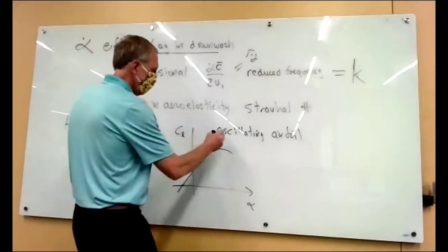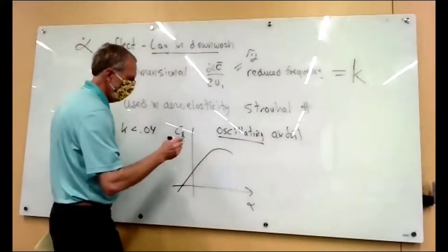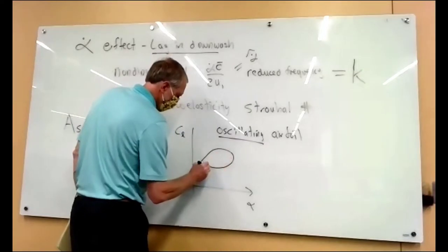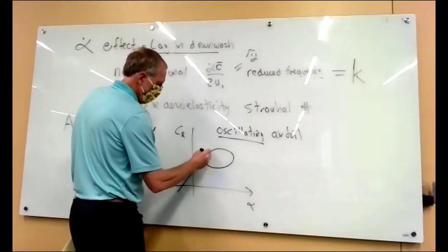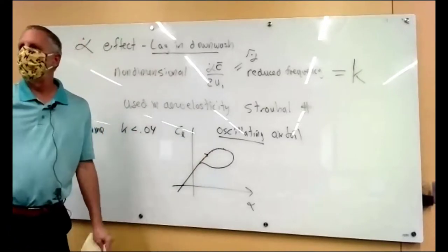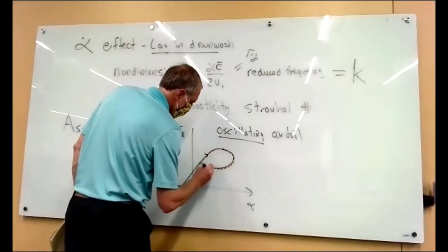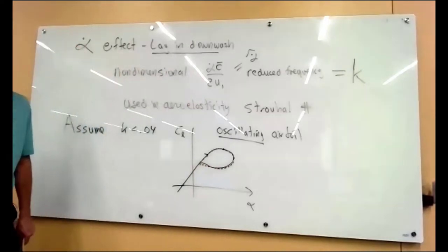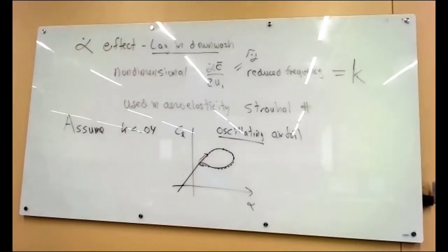If the airfoil is oscillating, that is, alpha is varying, say, plus or minus 1 degree, you actually get a curve that looks like this. On the upslope, when alpha is increasing, it follows this curve. But then when it starts pitching back down, there's a lag in the flow developing over the wing, and you get this curve. So it comes back on the downstroke to that value, and then if you go back up, then it goes back up like that. So that's an extra effect that we're not talking about. We're just talking about the lag of the downwash. So that's our model.